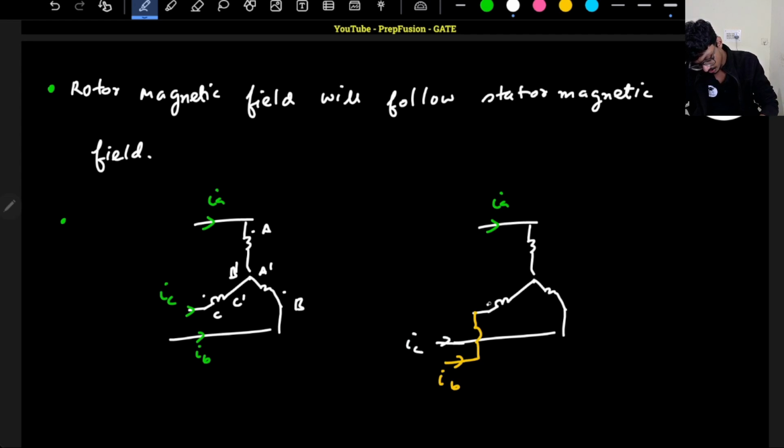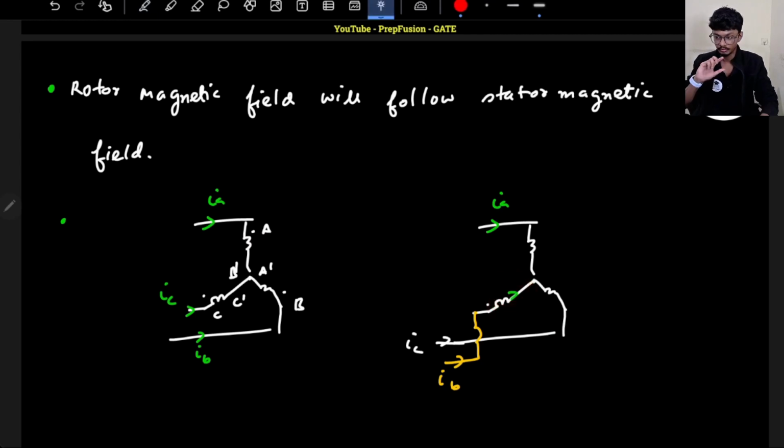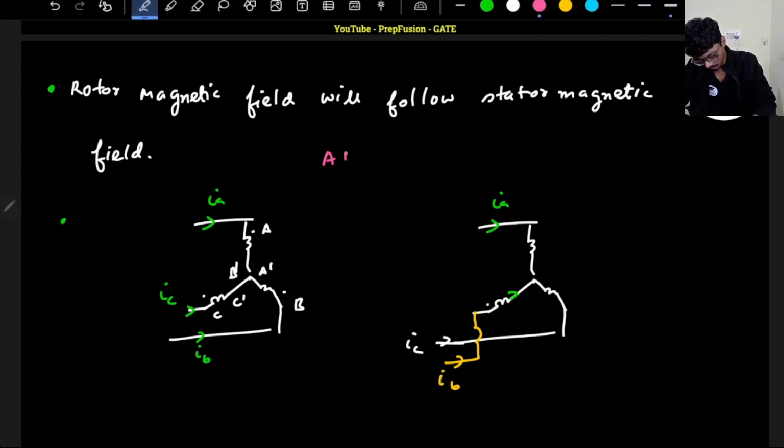So now this will be providing my IB and this will be providing my IC. The phase sequence has changed. Previously first A was coming, then B, then C. Now first the peak of A will come, but then the peak of B will come in this direction. Phase sequence basically means whose peak comes first. Generally ABC is the phase sequence of the supply, that we know.